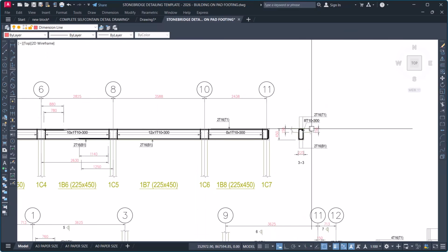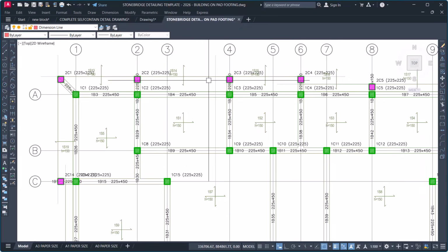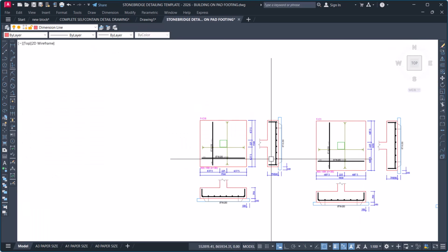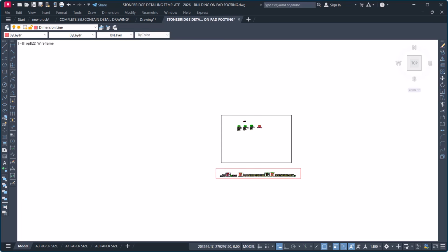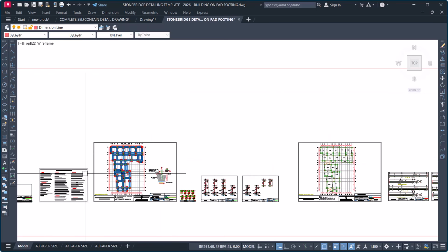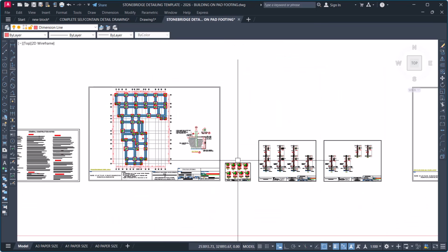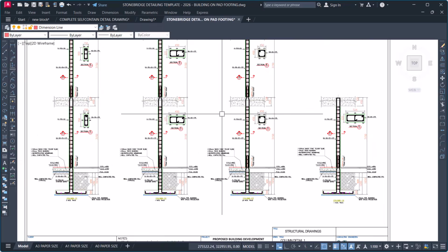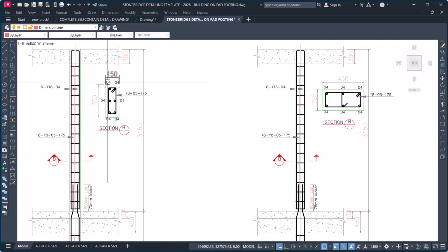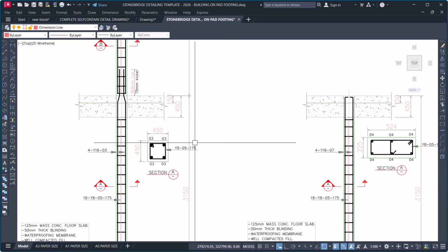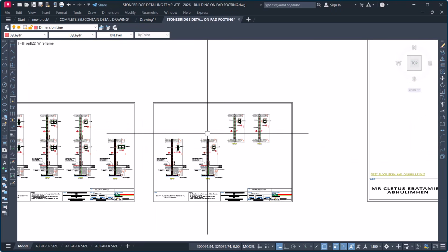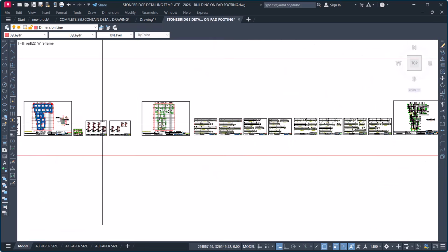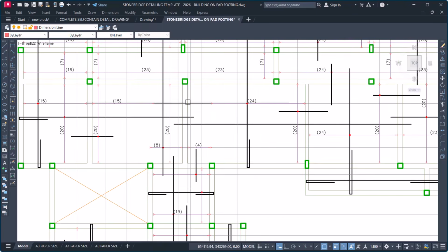So this is correct. Now, once you have done this, the next thing to do is put your drawings in sheets, and also optimize your footing, to have something like this: an endpoint as a layout, the section, and the footing details. Then the column details, where we transfer the schedule details that came from there into this place. We also have a column that starts from the beam to the roof like this, then the layout for the first floor, and then the slab detail. You can see the slab here and the section.